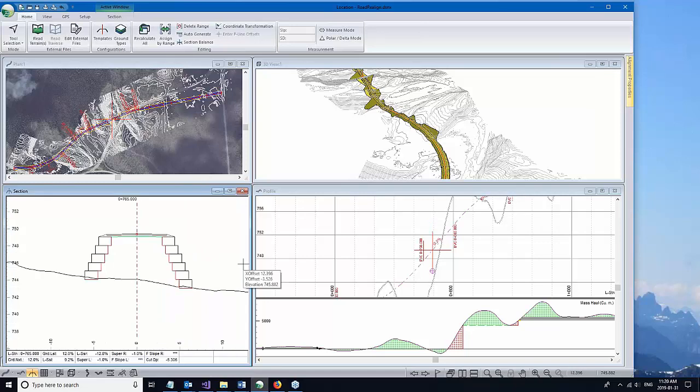As a general rule, it's best to minimize the number of templates that you have. It's just an organizational thing. I would definitely try to keep the templates at a minimum, and I'll talk about this a bit more later, override parameters or use reference features to force the template to do different things rather than creating, I've seen lots of designs will have 15 or even 20 templates. Really try and avoid that because it's just adding complexity to your design. Simple is good.